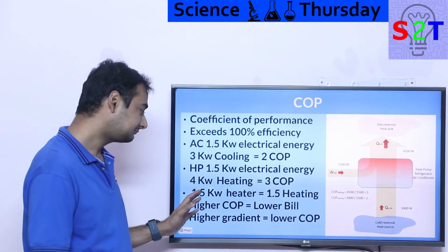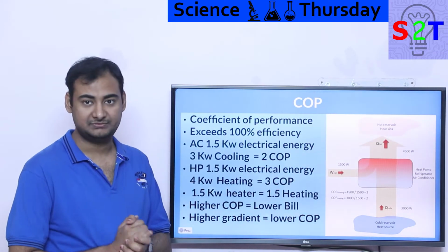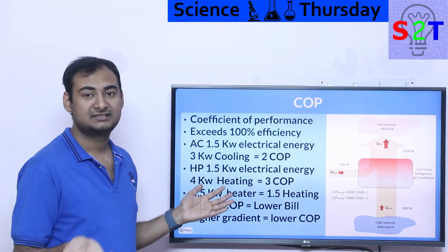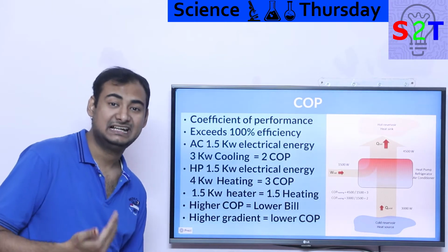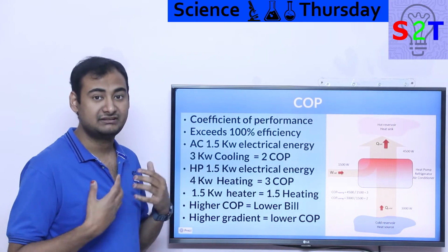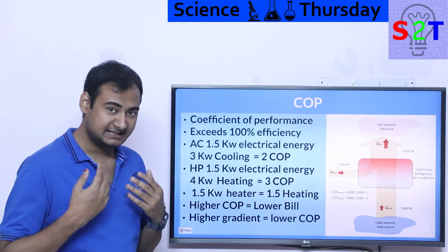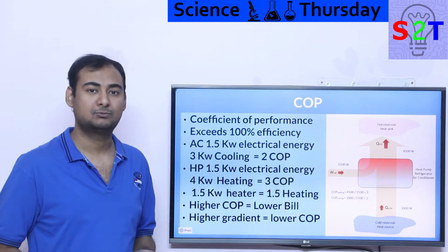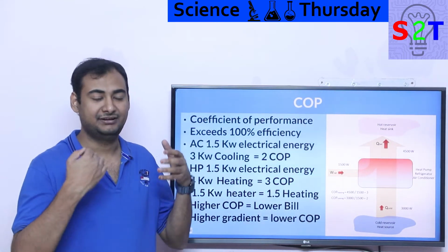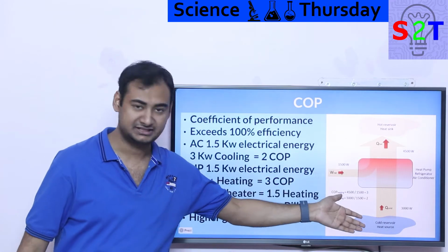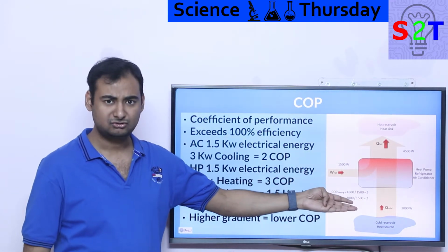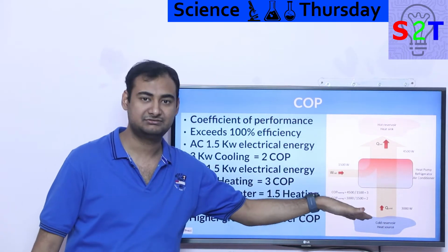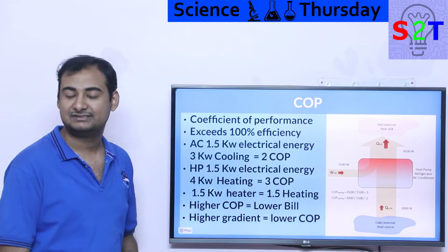won't be very accurate. So what does higher COP mean? Basically, if your air conditioner goes to, let's say, 1.5 COP versus 2.4 COP, what does that translate to? That simply means you have to consume less energy. Your power bill, air conditioners are very heavy on energy consumption, and that is the primary reason, because most of the time the COP is not very high. It's generally when you are forcing your air conditioner to work the hardest, when it's near impossible to dump the heat from, let's say, a room that is 20 degrees Celsius, that is your intended temperature, and somehow dump the energy from 20 degrees Celsius into 50 degrees Celsius. It's not very efficient.